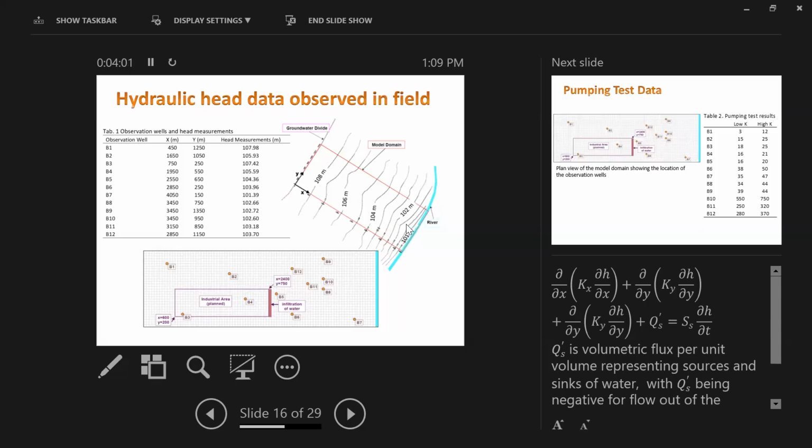Okay, so we define our boundary condition. This is how we create a conceptual model. In the conceptual model, we add all these parts. In our conceptual model, we also define K. Here we define different values for K in different zones, like we created these 6 zones, and we assign a value. Each one will have a different conceptual model with respect to K because each one is different. But with respect to this boundary, I think we all will have the same.